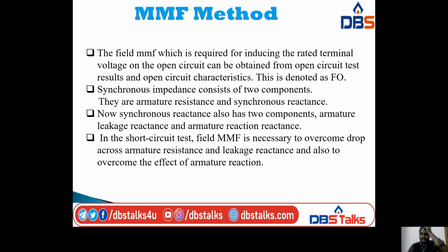Synchronous impedance consists of two components: armature resistance, that is Ra, and synchronous reactance, that is Xs. The synchronous reactance also has two components: armature leakage reactance, that is XL, and armature reaction reactance, that is XA.